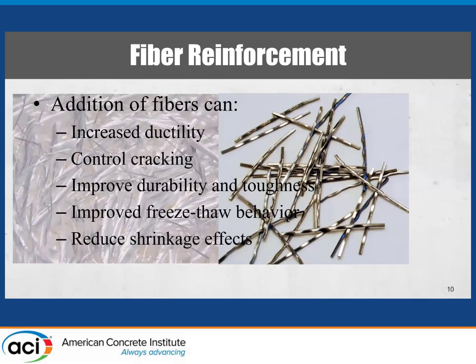Fiber reinforcement might be another way. Again, the benefits of fiber reinforcement: you can get increased ductility. You're going to control cracking, improve the durability and toughness of your building or structure, improve the freeze-thaw behavior, and reduce shrinkage effects. So these are all ways in which today, using current technology and current building codes, you can still increase the resilience of your structures without going to designing for higher loads or a performance-based design.